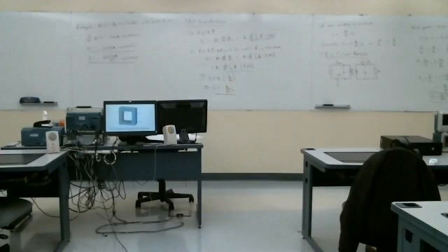Now, a couple of things here. Often if you're given a circuit, you're free to pick the polarities. You can pick V2 to have whatever polarity you want. The same may be true for V1. So it's usually convenient to put the assumed plus terminal at the dots. You don't have to do that. If I'd chosen V2 so it was positive at the bottom, then I'd have a minus sign in here.